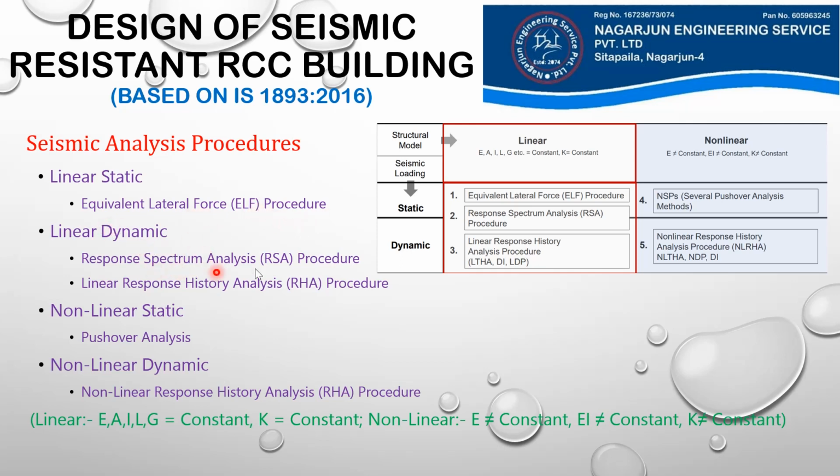For linear dynamic, we have two methods. Response spectrum analysis is not a totally dynamic process. Some part seems static, some part seems dynamic. It is some sort of pseudo-dynamic process of analysis, or we can perform linear dynamic analysis by the linear response history analysis procedure. In nonlinear static, we have pushover analysis.